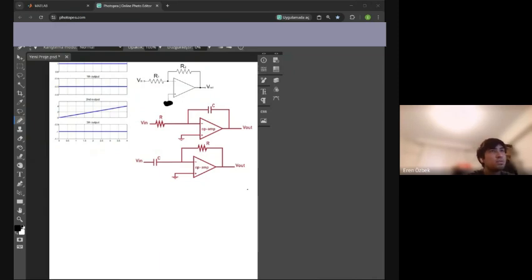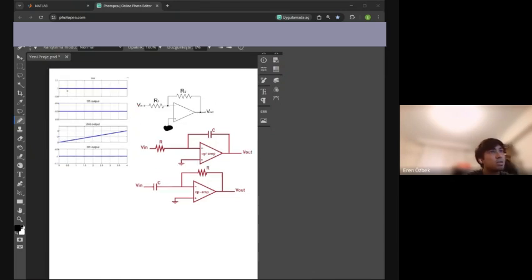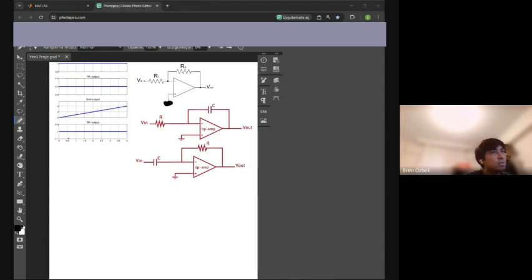We analyze the waveform from left to right and determine the type and component values of each stage. At the first stage, we observe the input is a constant DC value of 1 and the output is a constant DC voltage of opposite sign. Analyzing both, the output is the input inverted and scaled by a constant factor.